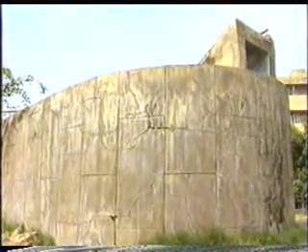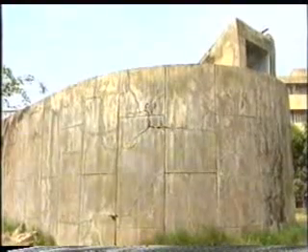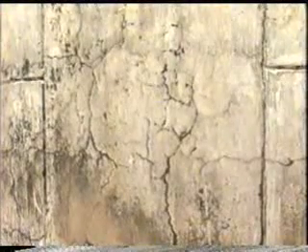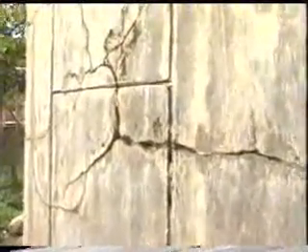Soundness of cement can be attributed to the volumetric stability of cement during the hardening process. In cement, cracks are developed due to the slaking of free lime and magnesia with water, which is due to increase in volume of set cement mass.